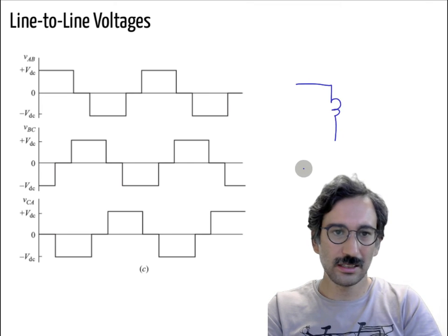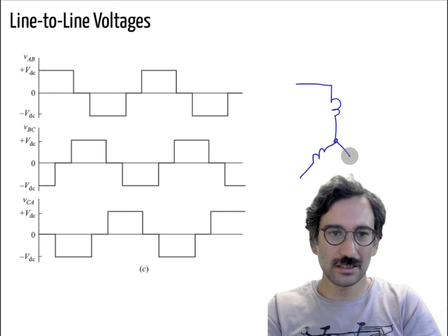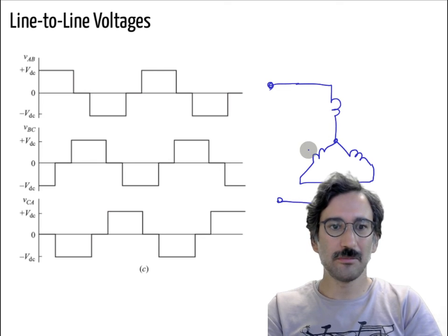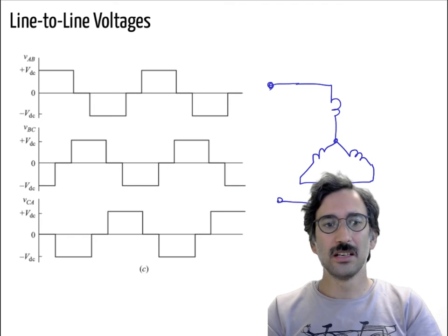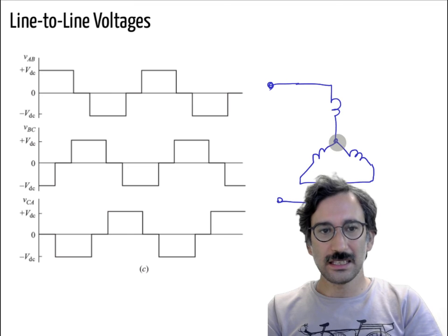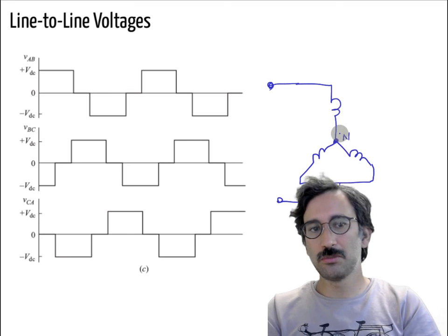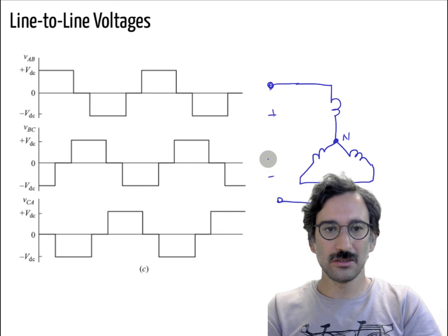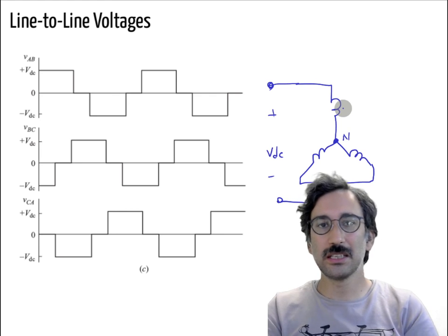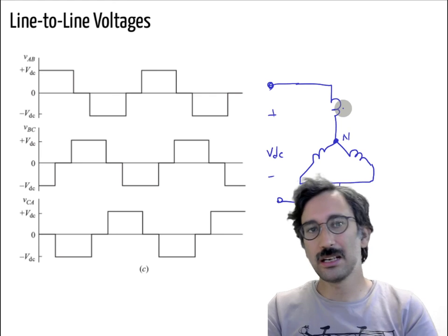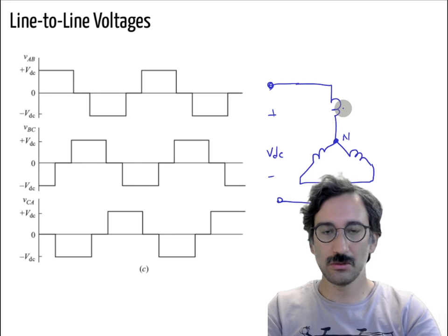draw it here again, at every switching state, two of your phases will be connected, something like that. It can be A, B, C. So there are 6 different combinations. And if that neutral point is floating, and this is your VDC, then the sharing, if you want to calculate the actual phase voltages, will not be VDC over 2, right? It will be either VDC over 3 or 2 VDC over 3.